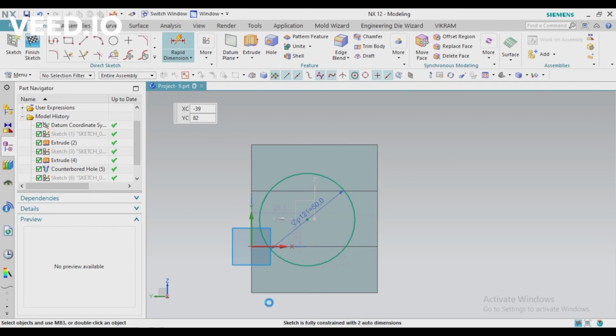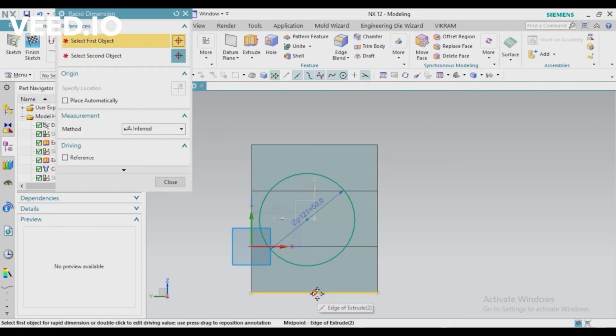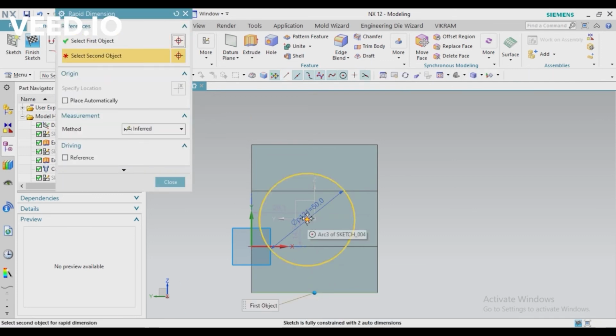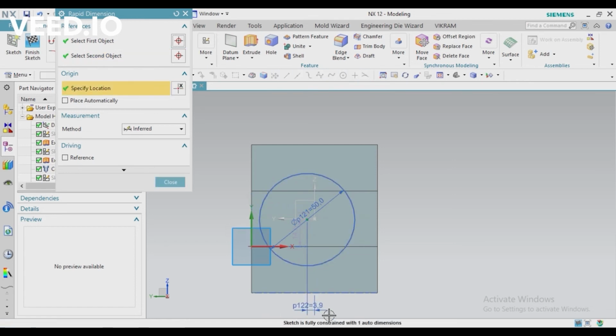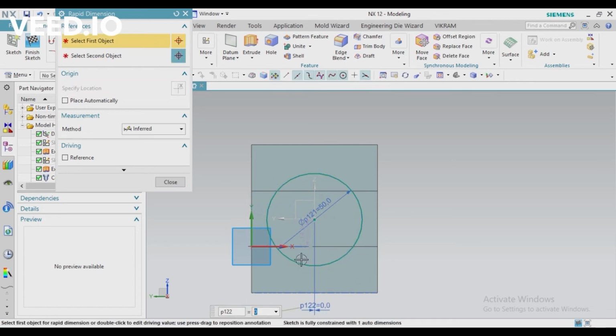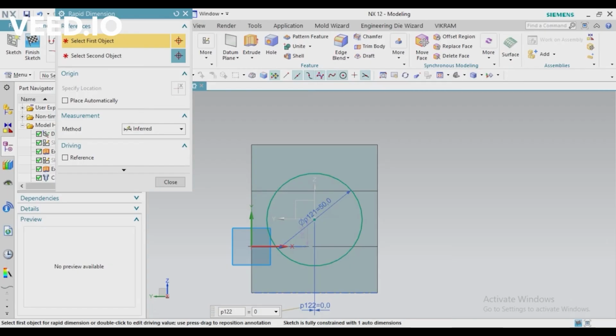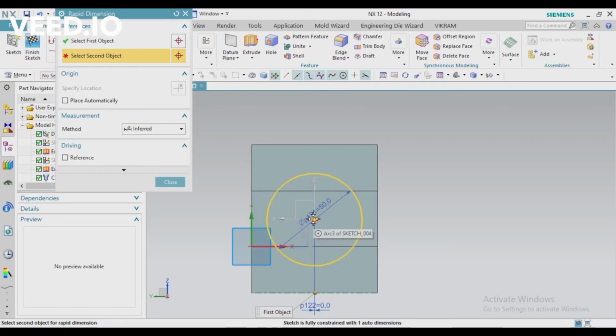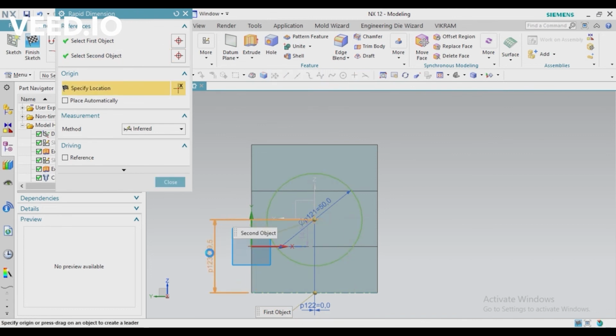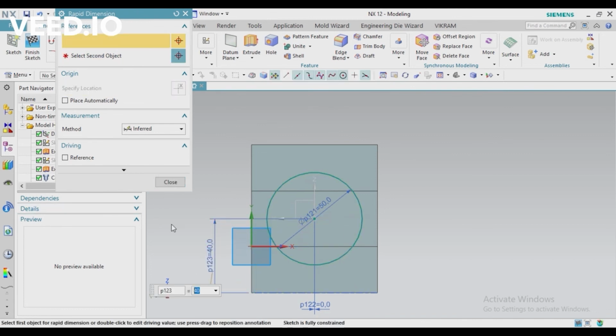Now you have to define your position. So you know this is in center, so you can use coincident or you can apply 0 mm distance. Okay, now we need only a half cutter. You can see dotted line in bottom only, not in top. Okay, so just also first you define this position. Actually I forgot to define.